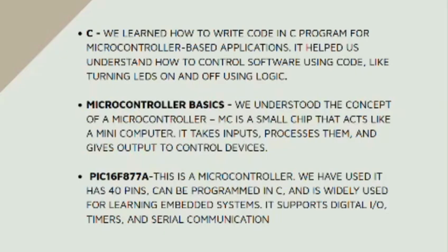It is used in embedded systems also, because due to this only it runs the washing machine. This is the main component. PIC16F877A is the main component in the washing machine. Due to this, it also runs. This is a microcontroller. We have used it; it has 40 pins, can be programmed in C and is widely used for learning embedded systems. It supports digital input, timers and serial communication.